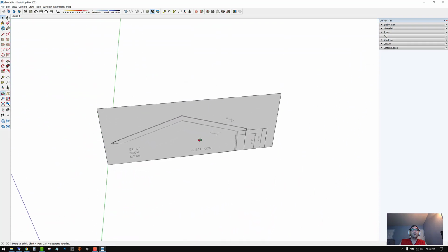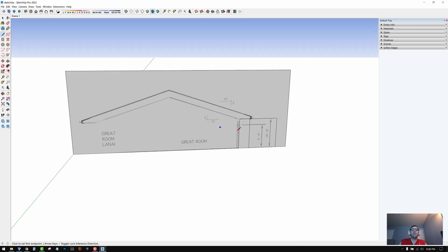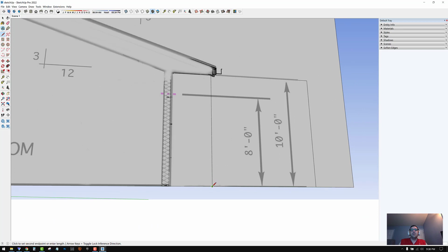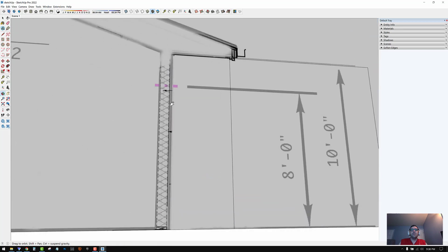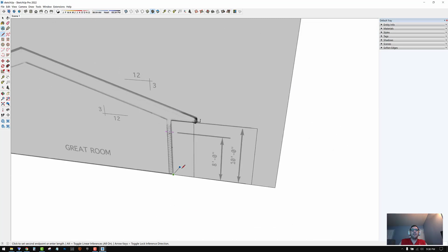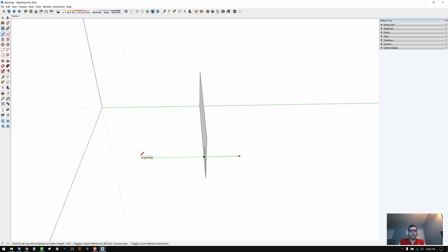I'm going to make a room that's 30 feet by 40 feet. So over here, I'll draw a line over to the starting of my wall, and I'll get that point, and I'll go over. Since this is going to be 40 feet, I'll do 20 feet in each direction, so 20 enter, and then this direction will be 40 feet.